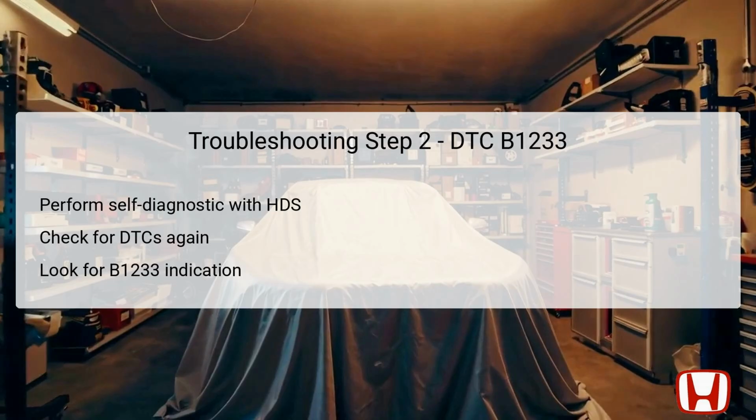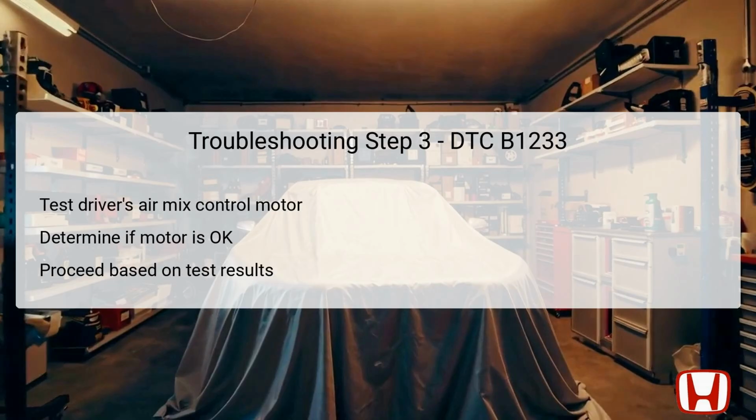Thus, recognizing whether B1233 is indicated once more will guide the next steps in troubleshooting. In the third step, turn the ignition switch back to the lock position and proceed to test the driver's air mix control motor. It is essential to assess whether this component is functioning as intended.